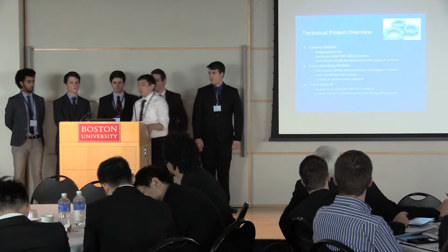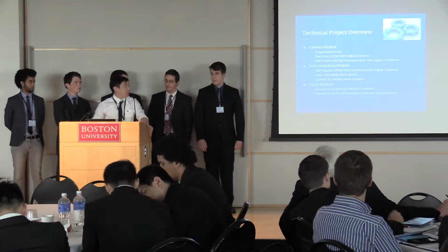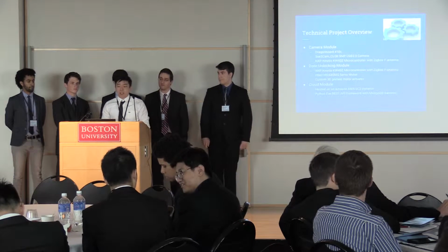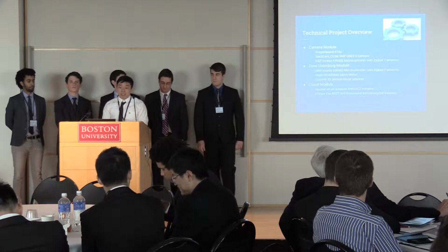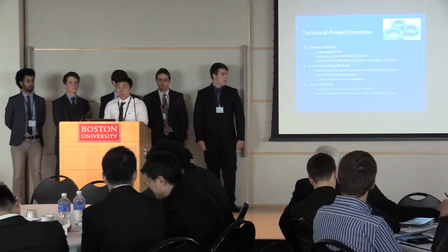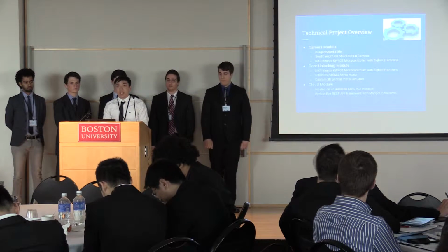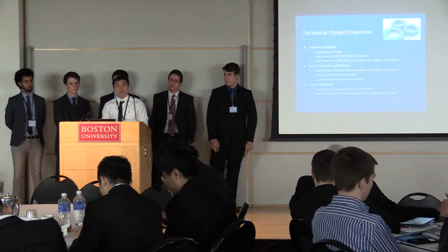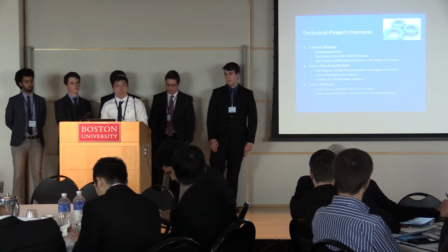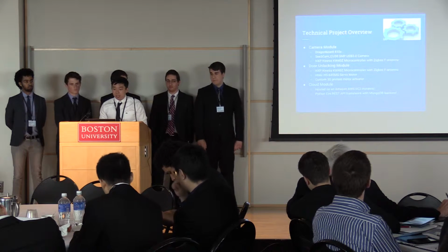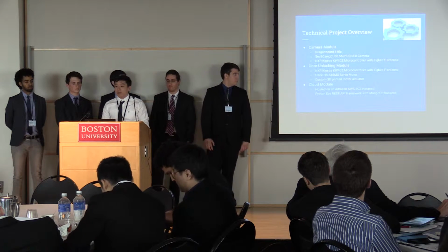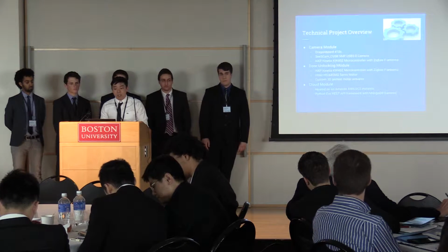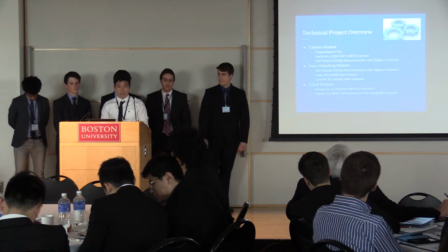So I'm just gonna go over the technical specs for each module. We have three main components to our project: the camera, the lock, and the cloud. The camera module is running a Dragon Board 410C development board. It's like a board that houses a Qualcomm Snapdragon processor, equivalent to processors you can find in your phone. We're also using a 5 megapixel USB 3.0 camera and a Kinetis chip for communication with the lock.